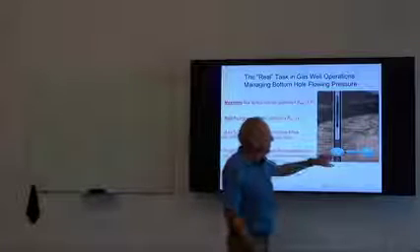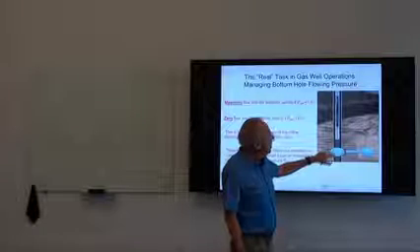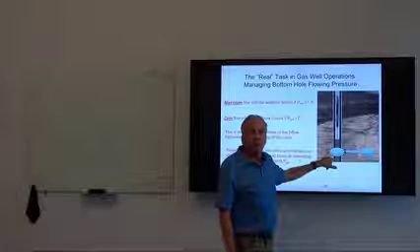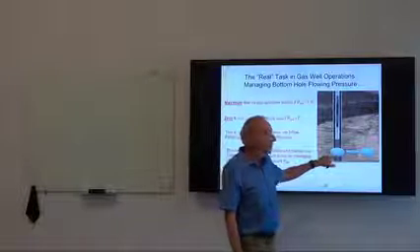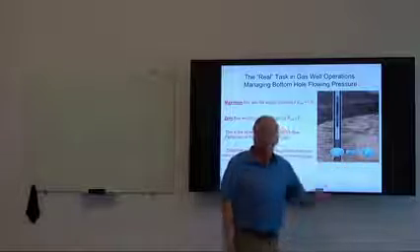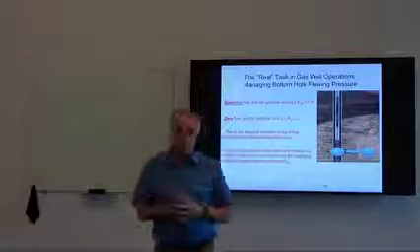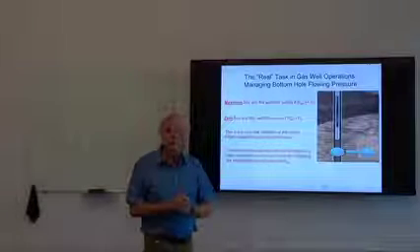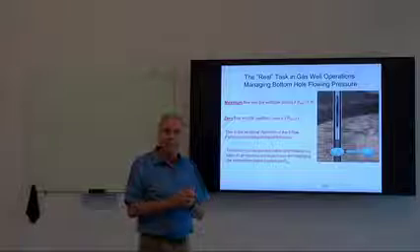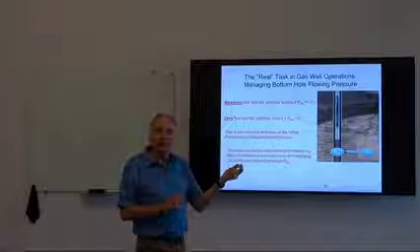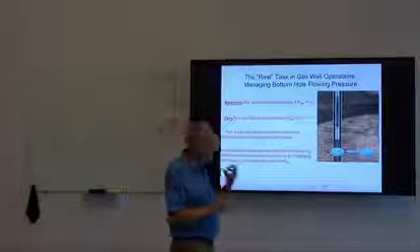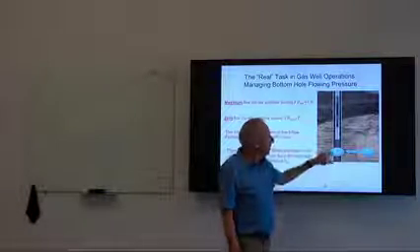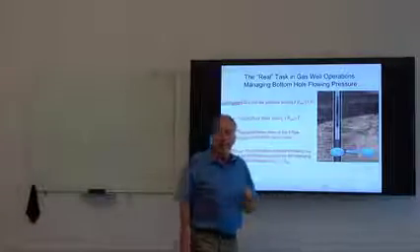If, on the other hand, we were to allow this pressure to rise, so that we put enough liquid in the well that this pressure bottom hole is increased by the hydrostatic pressure so that it is equal to the formation pressure, then we could actually take the flow totally to zero. And this is exactly what we just witnessed with that progression of liquid loading. Went from a maximum flow rate with low bottom hole pressure to zero flow rate when we had a high bottom hole pressure.